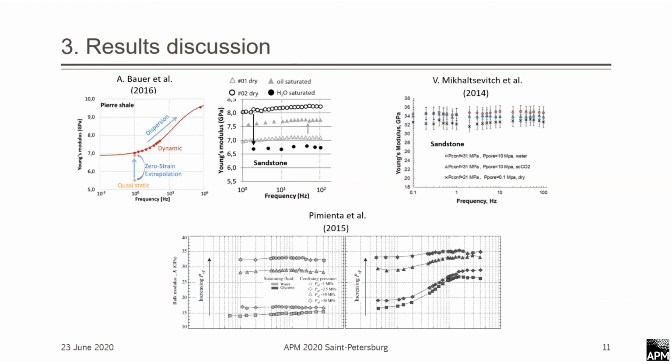According to the well-known fact, the Young modulus increases with compaction of the rock, so with larger loads the Young modulus is higher. When we apply force, micro cracks and pores in the rock close, the rock compacts, and the Young modulus increases.